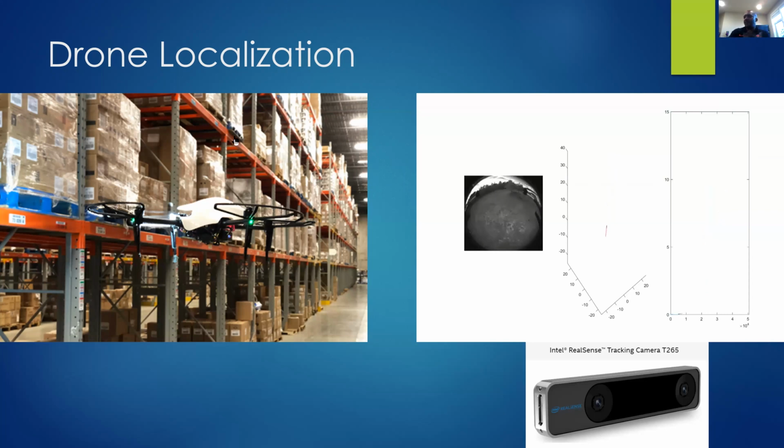Mainly, you can use the shelves as fiducials to some extent. There's some type of guide. A lot of times I don't really care whether I'm 10 centimeters from the aisle, I just care about the column. So I'm in column number 1, column number 2, column number 3. And so you can get that information using, I did essentially just a color thresholding, and then did a little bit of smoothing, and that gives us a column and it gives us our height.